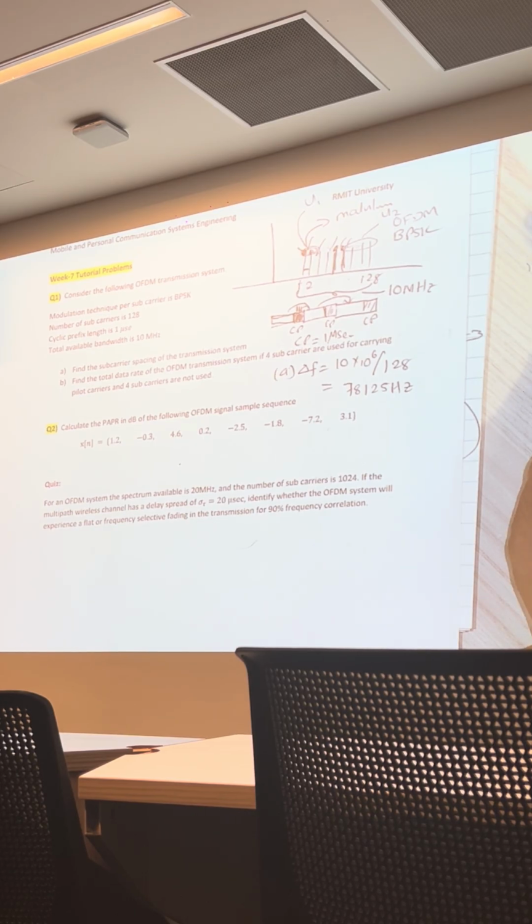transmission. So 4 subcarriers are for transmitting pilot tones, and another 4 subcarriers are not used, possibly guard bands at either end of the spectrum channel. So 8 subcarriers are not used for data transmission.